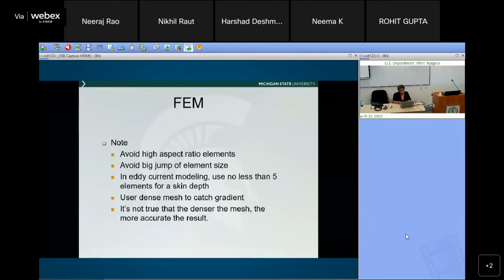So you have to avoid big jumps in element size. Typically, wherever there is a large gradient, near the defect, the field is going to change very fast. By Nyquist sampling, applying the same criterion, you've got to use smaller elements there. You've got to sample closer when the field is changing very fast. If the field is going to be very slow, then I can sample at larger spaces, so my elements can be larger. And you want to minimize the number of elements used so that your matrix equation is smaller, and those are the kind of things.